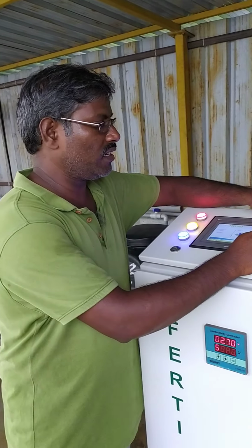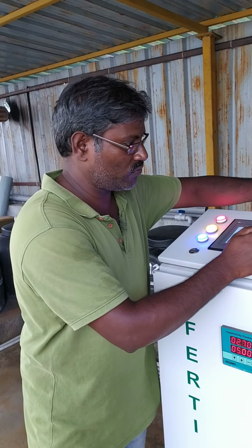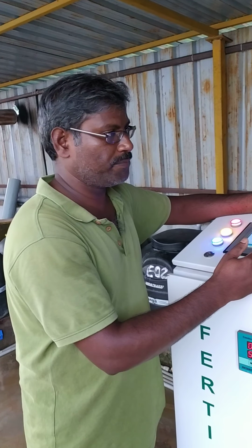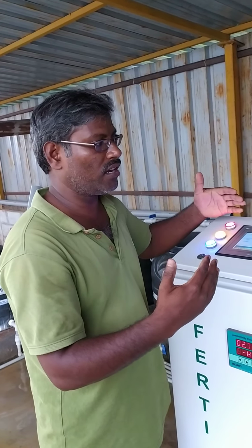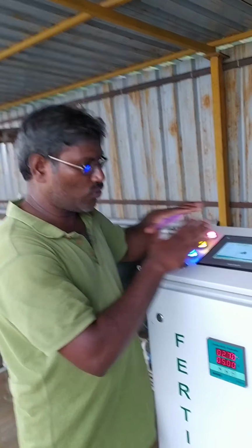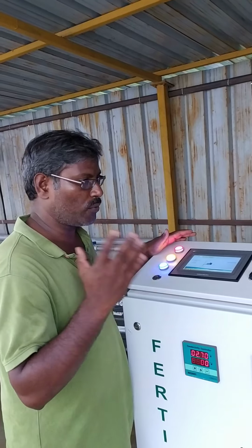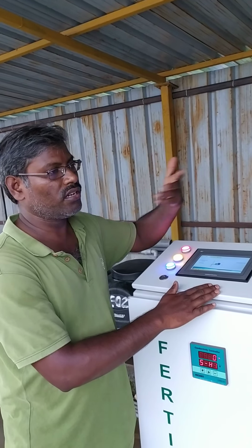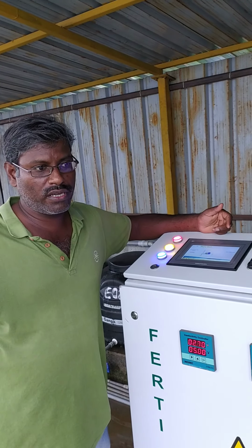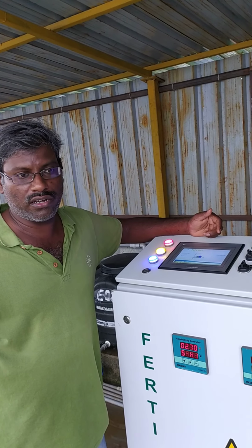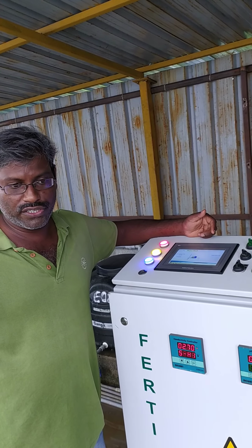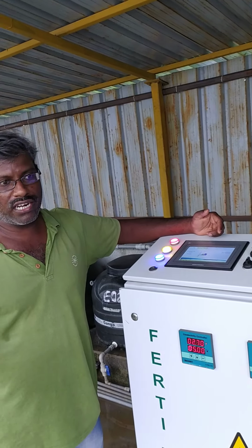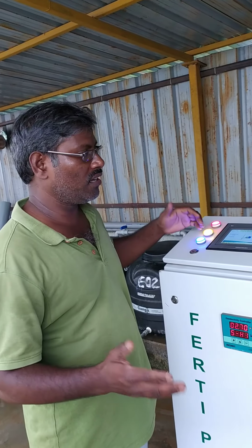When you switch here, the process pump and your sump pump can be switched, and the dosing valves can be switched here. You need to monitor a little closely to control your EC and pH, because it's more or less like a manual process, since in the worst case you are still doing it to control your process. You need to regulate your valves in that case. The field valves have to be operated manually, so you have to walk to the field and change the valve mode to manual mode. Then water goes to the crop. That way you can manage for a day or a couple of days till the machine gets rectified.